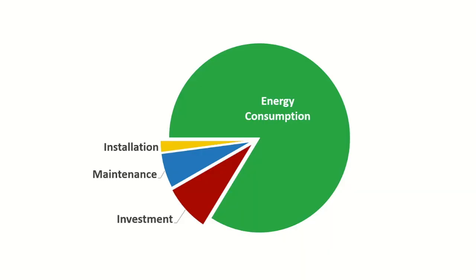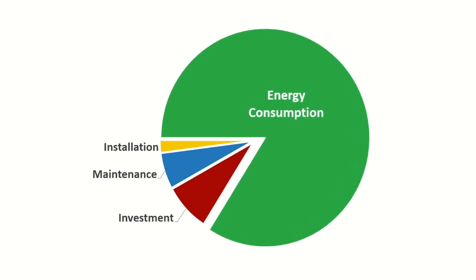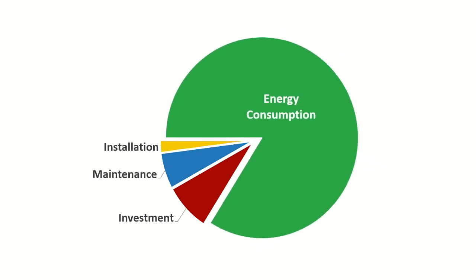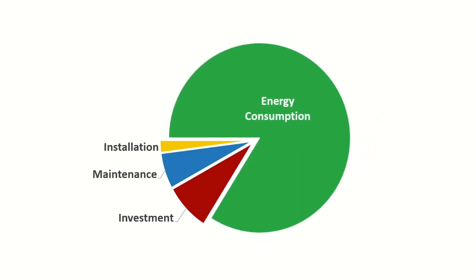When dealing with compressed air economics, it's important to understand not only the upfront cost of buying a compressor, but how much it costs to operate it over its lifetime. This chart shows the typical life cycle cost of an air compressor, and as you can see, most of the cost comes from operation rather than the initial investment of purchasing the compressor. In fact, it typically only takes 12 months for the operating costs to exceed the initial purchase cost. So if your plant is in need of a new compressor, don't get too hung up on the initial cost up front. Instead, focus on managing air use.